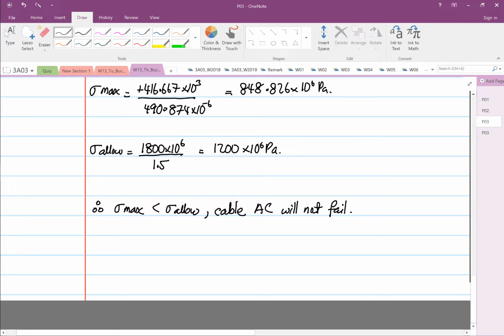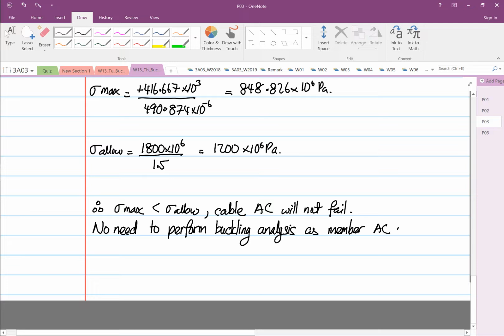Okay, I know we have written this down already, so we also declare no need to perform buckling analysis, as member AC is under tension.